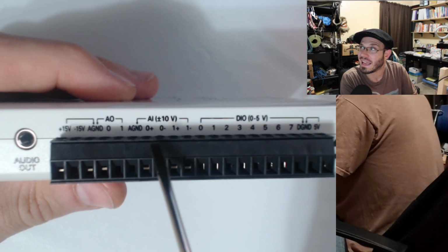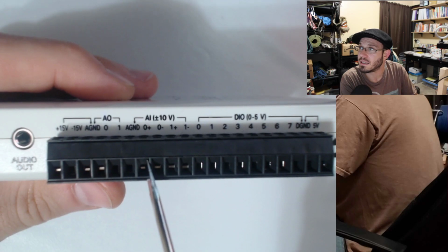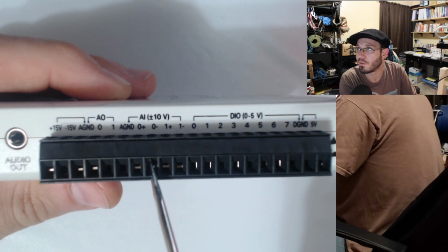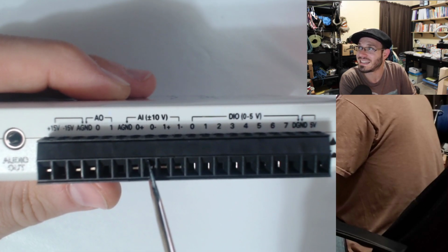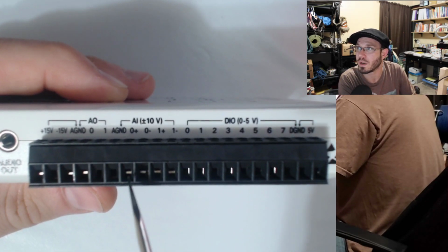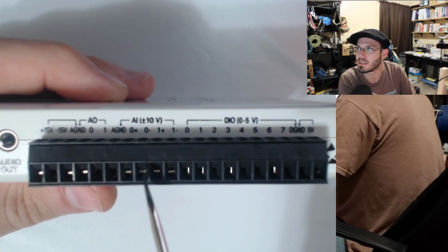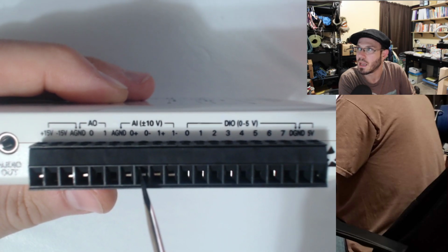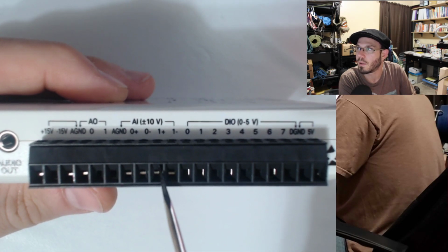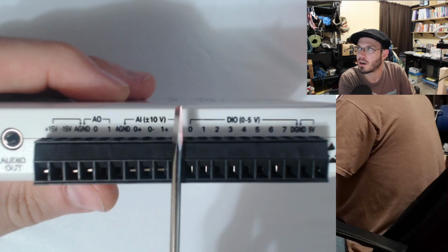We also have our analog input. This is for the oscilloscope. And for the oscilloscope, each channel has a positive and a minus. So whenever you're viewing a voltage or whenever you're measuring a voltage, you're going to be measuring it in reference to something, right? I don't have a voltage at only one point. I have a voltage between a point and something else. So we're going to need a minus and a positive for each one of our channels. And so we have a channel 0 with a positive and minus, and we have a channel 1 positive and minus as well.